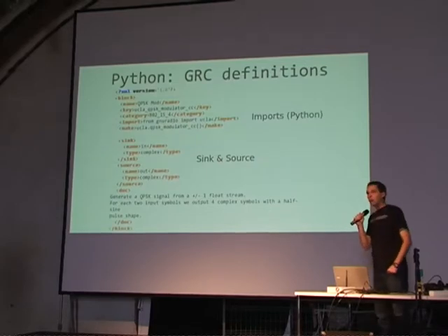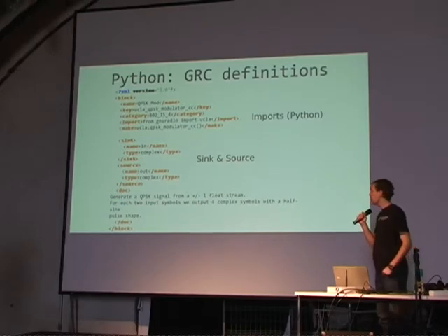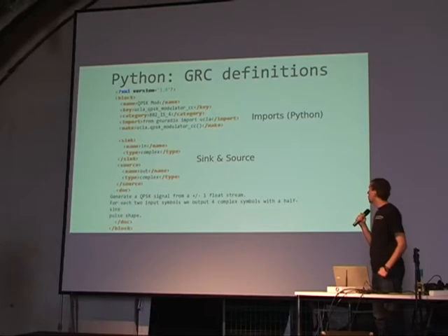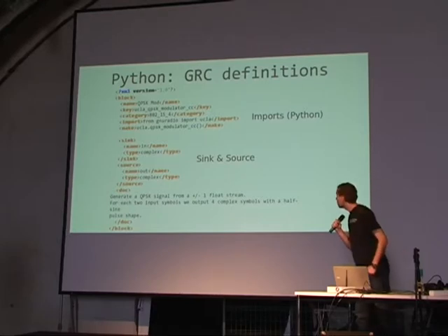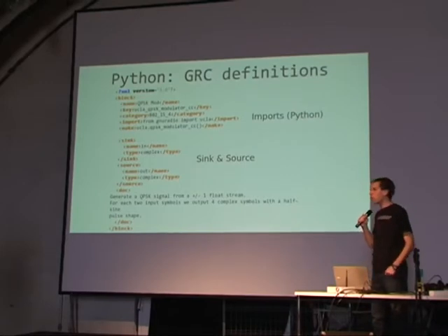I've mentioned that the blocks, and I'll show this later in a graphical representation, are created in XML. So what you see is that you define an XML scheme and put in your values, and you expose this file to the GNU Radio Companion. And afterwards, what is this showing? The QPSK modulation available in the GNU Radio Companion, and you can use it for each transmission scheme you want to have it.